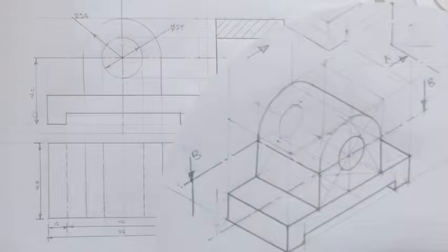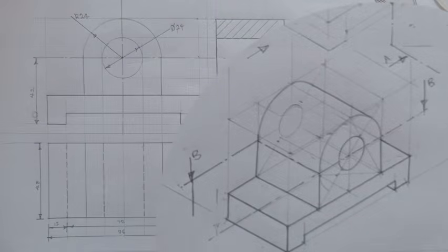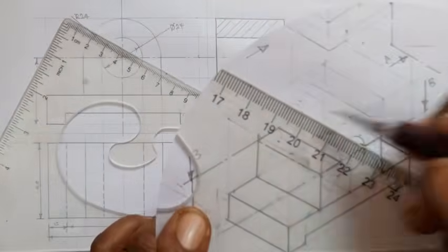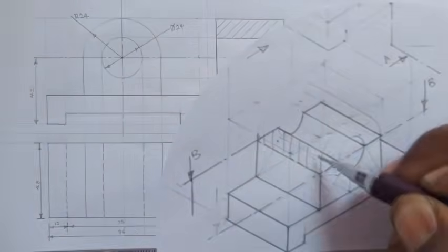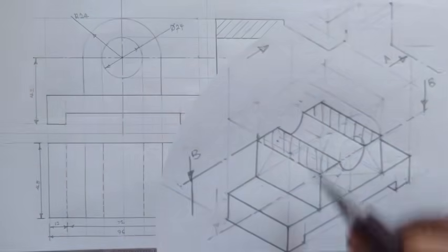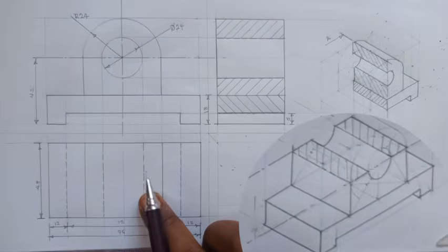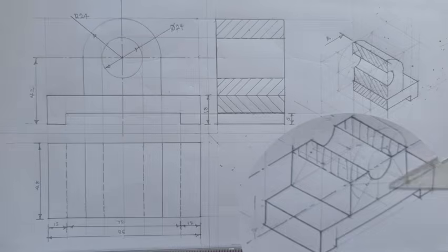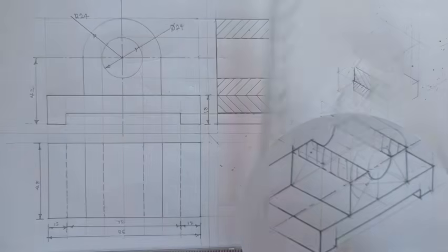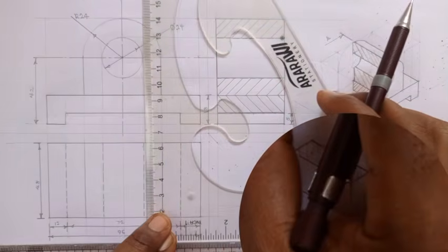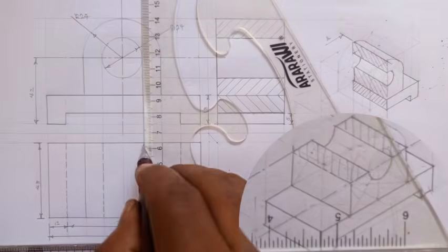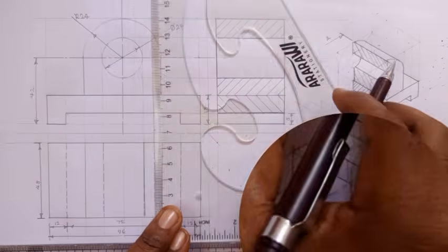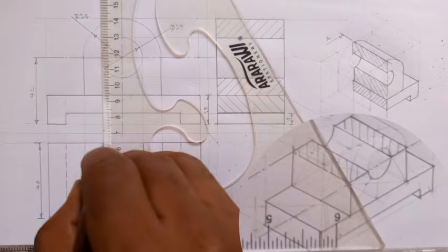So we're looking at it from the top after we've sectioned it. So what we'll do is this. Looking at it from the top. So I'll come here. Don't you see? If I come here, it means that this hidden line will become a thick line. Right? This will become a thick line. Then it will become a thick line this way. And here also a thick line this way.